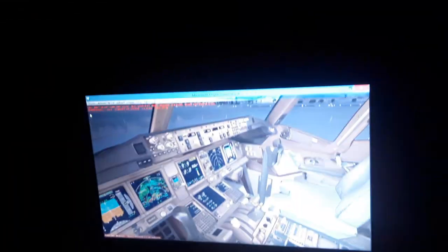So then I'm gonna come to the autopilot and flight director system panel, the FDS. Now also the autopilot engage and disengage switch, the autothrottle left and autothrottle right engage and disengage switch, the flight director engage and disengage switch, the airspeed selection knob. We're going to select an airspeed for the airspeed guidance of the aircraft in knots, or Mach speed.